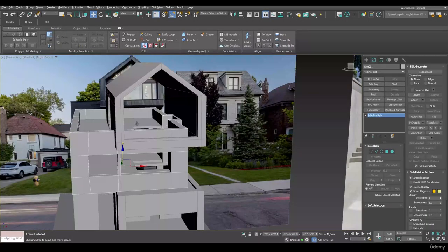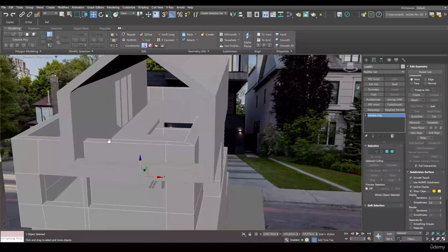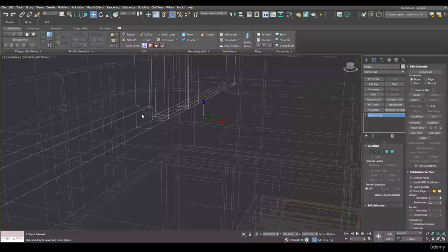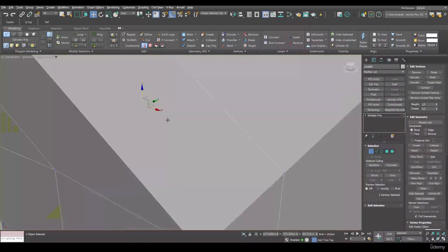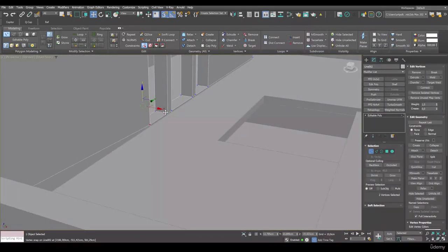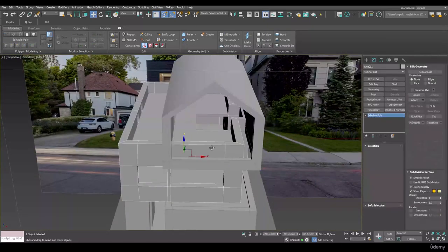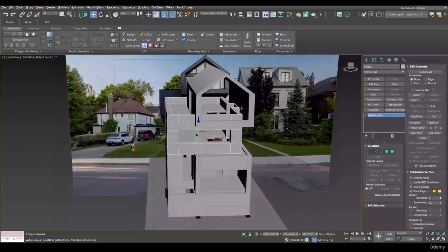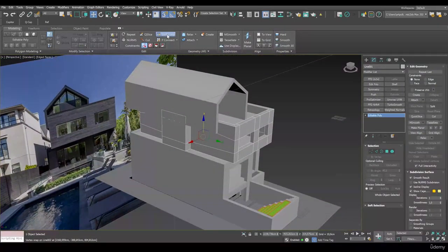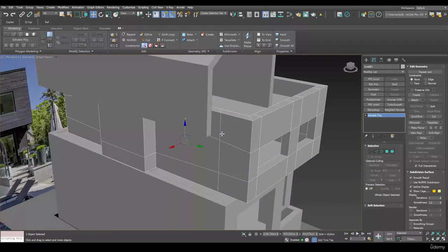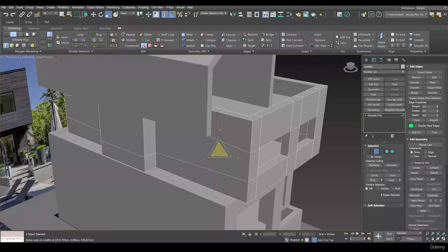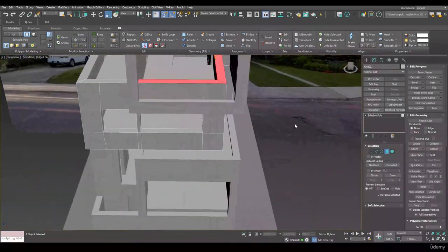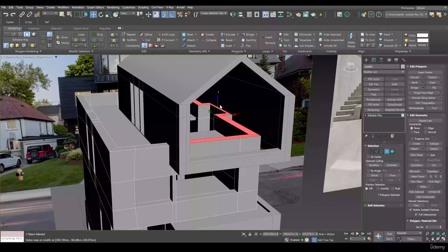Inside the previous floor crosses the space of our top floor. So we need to fix that. I also noticed a small mistake on the door here. An accidentally protracted point. We can fix it right away. And now to correct this detail intersecting our next floor, we can use the Smart Extrude tool. And to do this, we add one more ring of edges, and using Smart Extrude, having selected this part, we hold Shift and move the polygons down.